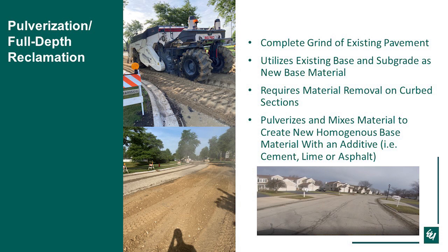You can typically do anywhere from, I want to say, 8 to 16 inches deep of reclamation, and then it would put down the new base, which is shown there in the bottom left, and what's shown in the bottom right is what the existing roadway looked like. This particular project that we utilized it in was an area where the community had existing pozzolanic base and had a lot of issues with freeze-thaw, and we were able to use this full depth reclamation to remediate that and put it back down.